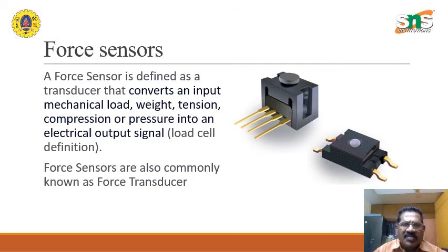A force sensor is defined as a transducer that converts an input mechanical load of weight, tension, compression, or pressure into an electrical output signal, or the load cell definition. Force sensors are also commonly known as force transducers.